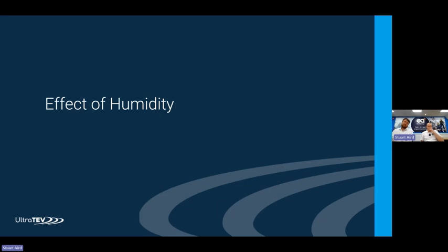Thanks, Chip. It's quite topical. Anyone in the UK, unfortunately, probably suffered the storm last week, and quite a few areas were flooded. So humidity in the substation might be a permanent thing. It might be there because of where the site's situated, etc. But it can also be a very temporary thing, something that comes through flooding, and the damage is caused. The PD starts at that point, the deterioration starts. You're happy your site's dried out, everything goes back to normal, but that deterioration continues over time. So if you have had any sites that have had flood damage, I would recommend considering that, following up on what the impact of that might be, and checking going forward.